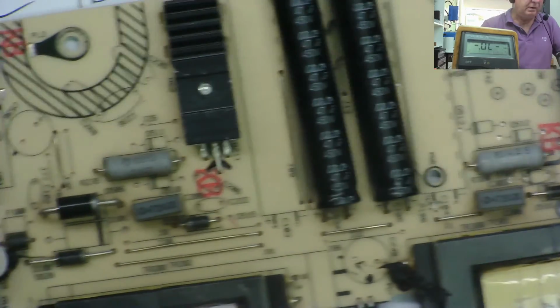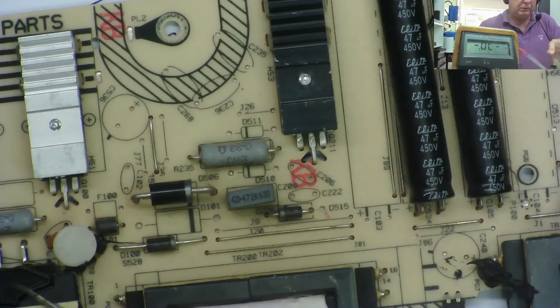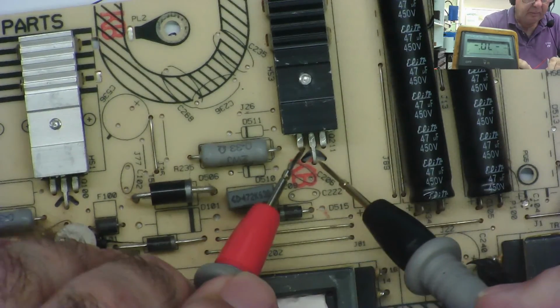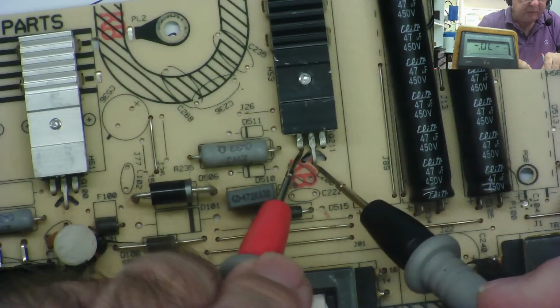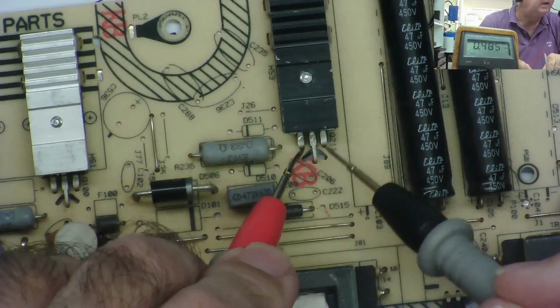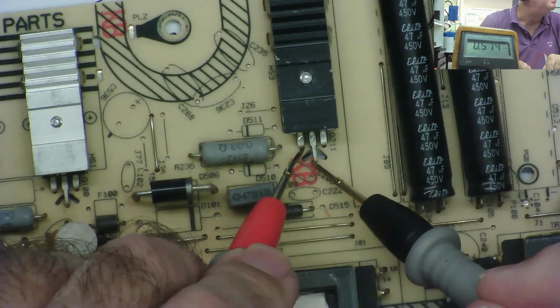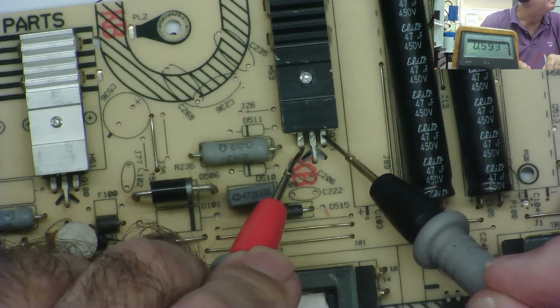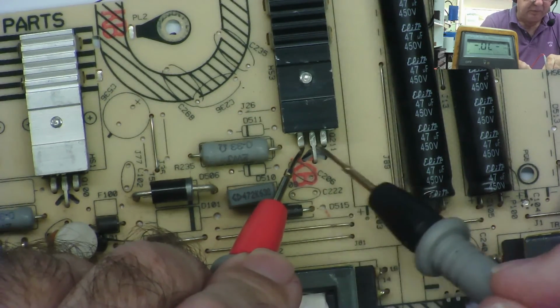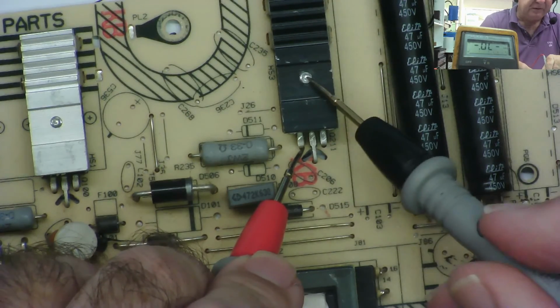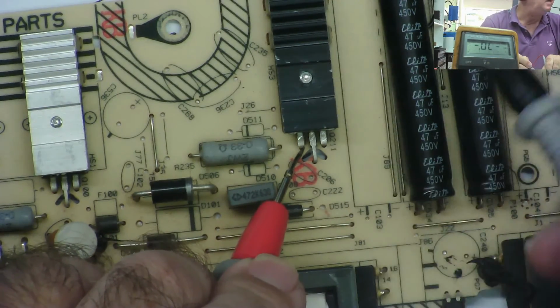There's a couple more over here. Let's have a look at these. So what have we got on this one? Again, let's assume this is the base first. Yeah, we've got a diode junction. We've got a diode junction. That's considerably higher than this one. 485, 592. That's collector emitter, you would think. And you assume the collector's in the middle and attached to the heatsink.